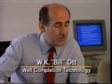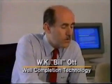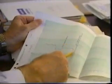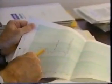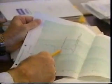Well, this first example we're going to look at is a workover which involved a matrix carbonate acid treatment to restore production. This particular well in West Texas was a carbonate at about 6,000 feet, and a casing leak developed which cut production from about 4,000 to 2,000 barrels per day.